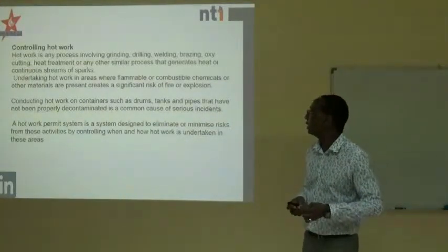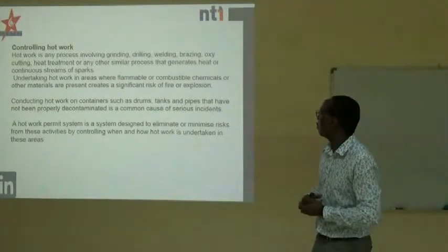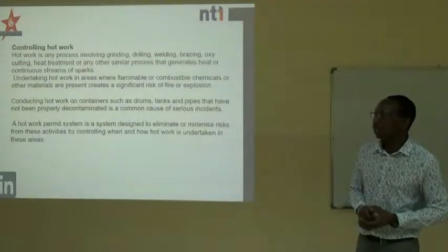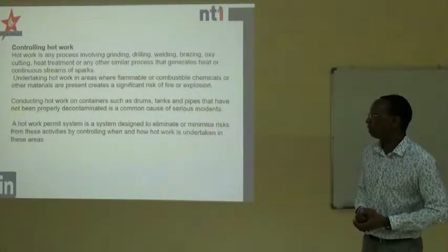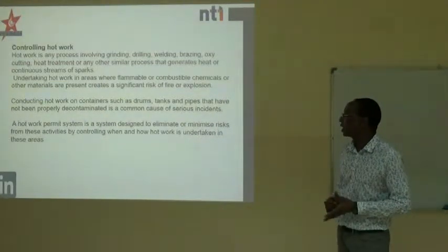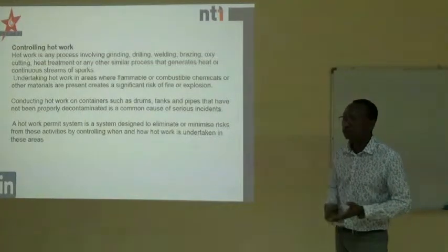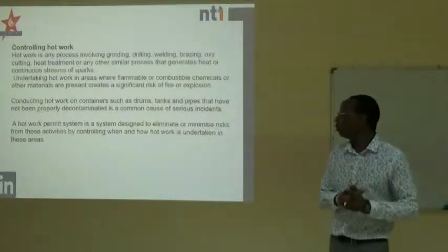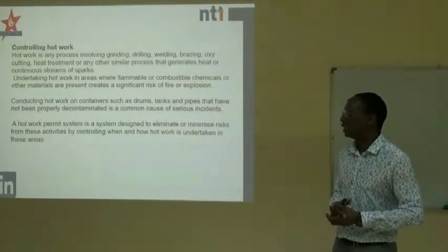Undertaking hot work in areas where flammable or combustible chemicals or other materials are present creates a significant risk of fire or explosion. So conducting hot work on containers such as drums, tanks, and pipes that have not been properly decontaminated is a common cause of serious accidents.